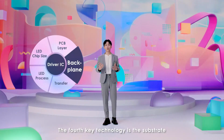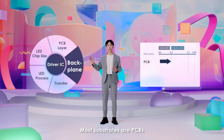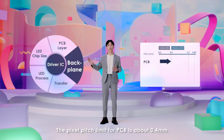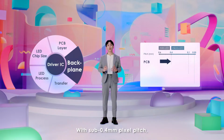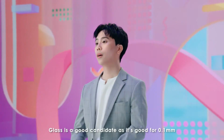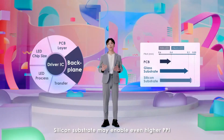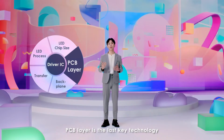The fourth key technology is the substrate. Most substrates are PCBs. The pixel pitch limit for PCB is about 0.4 millimeters. With sub 0.4 millimeter pixel pitch, mass transfer needs a flatter substrate. Glass is a good candidate as it's good for 0.1 millimeter. Silicon substrate may enable even higher PPI. PCB layer is the last key technology.